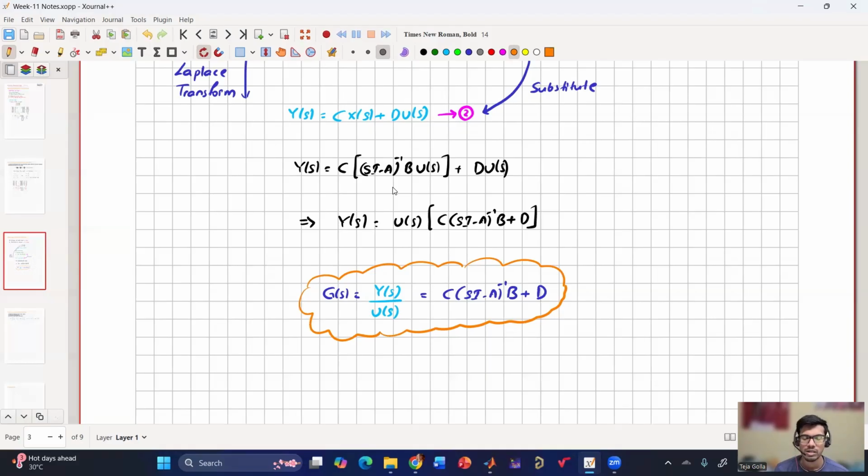For a given system, if it is multi-input multi-output, then it is not recommended to go by the transfer function based approach, and we should go by the state space approach. However, if it is single input single output, we can convert the given state space model into a transfer function, and whatever we are going to design, or whatever poles or stability we are going to check, we can check from the transfer function. But we are also learning how to correlate between these two: if one is given, how to calculate the other.